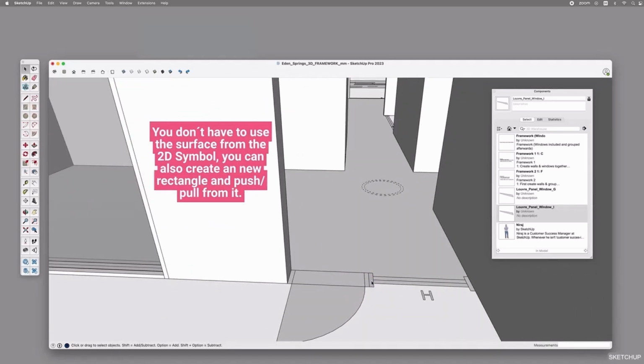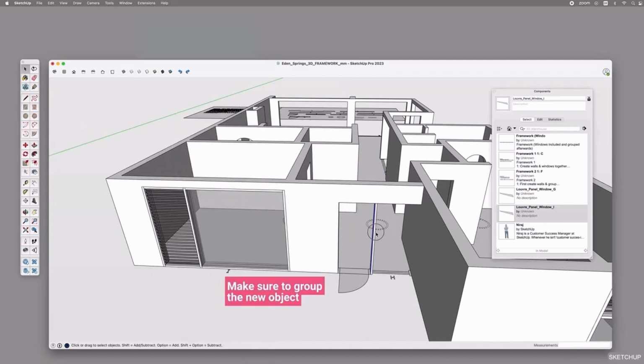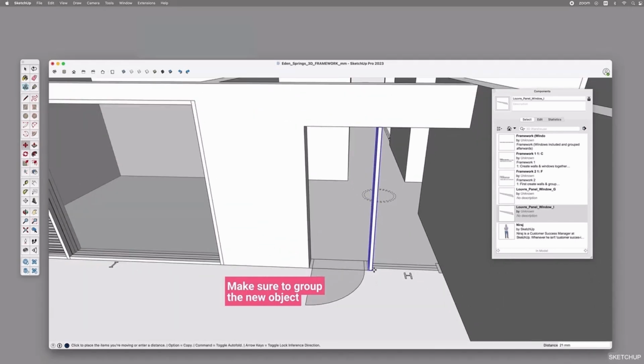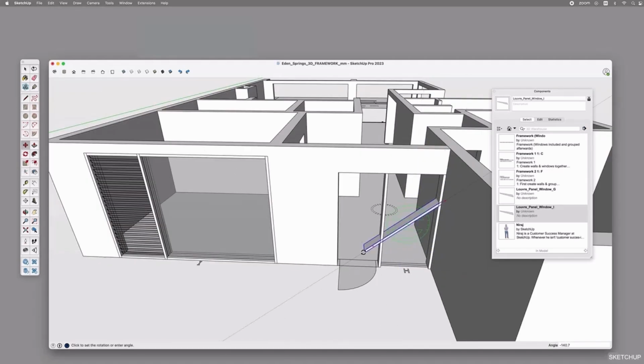This is kind of split. We have a door on the left and a window panel on the right side. So I'm going to leave out the door for now and just create window H. So create a frame, copy the frame to the side. So whatever you can make use of, just try to copy.